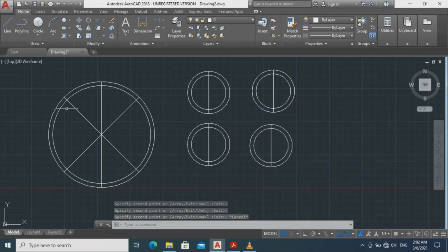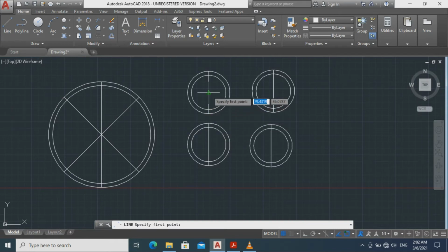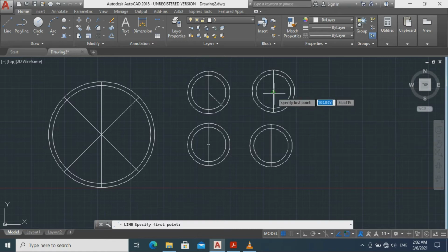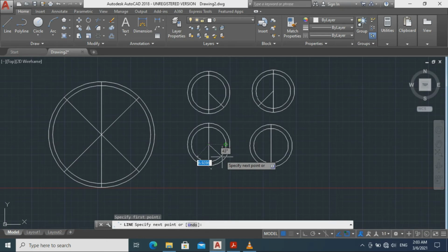So for us to connect here, we're going to add guidelines with their corresponding angles. So for this one, we're going to click here, then set that distance to 8, tab, then 45 degrees, and escape. So another one, let distance of 8, tab, 135 degrees. There you go. Another one, we have a line here, then here, let's set that at 8 and 45 degrees.